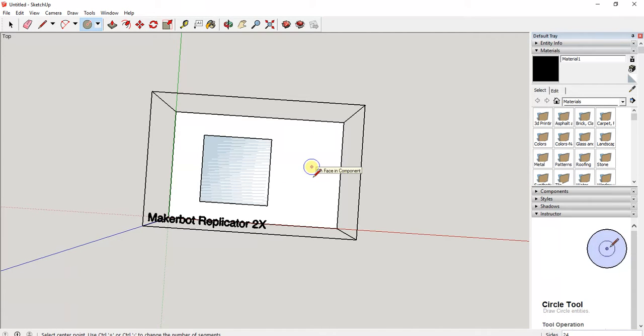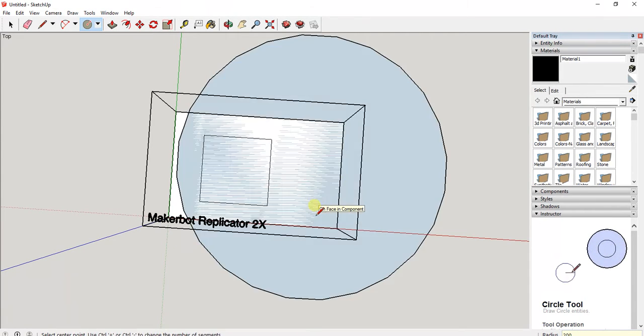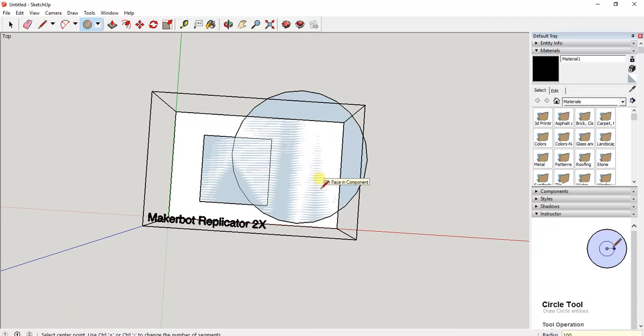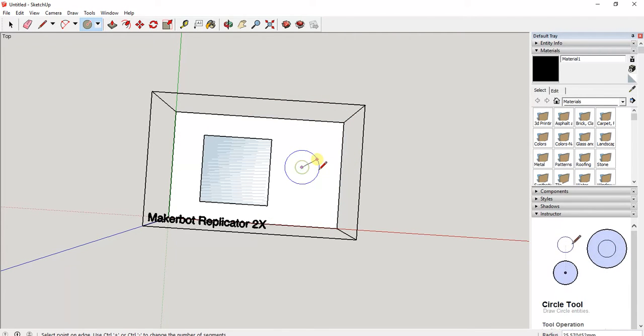So here's a circle, and if I click and start dragging out, it's doing the radius. All right. So to get a 10 centimeter diameter, we'd want to put a radius of 200? No. What do we need the radius of? Well, let's click and check. 100. No, it's still looking too big. So what's the difference here? Why isn't this working? A radius. Of course, we need to halve it. So that would be a 50 millimeter radius, which is going to make a 100 millimeter diameter circle.